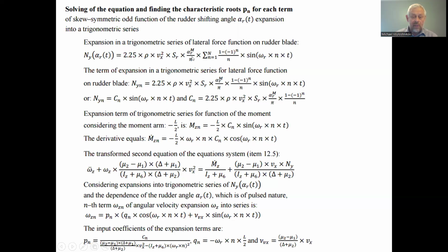All others dependent on the angle of the turning of the rudder, and the turning of the rudder itself is dependent on time. So for decision of the inhomogeneous equation, we have to consider the dependencies on time, because we consider the motion of ship on the surface of the water, assuming that the longitudinal motion of ship on the water is of the constant velocity, and the transverse velocity and the rotation velocity of ship in the associated ship coordinate system, we consider as variables subject to find.